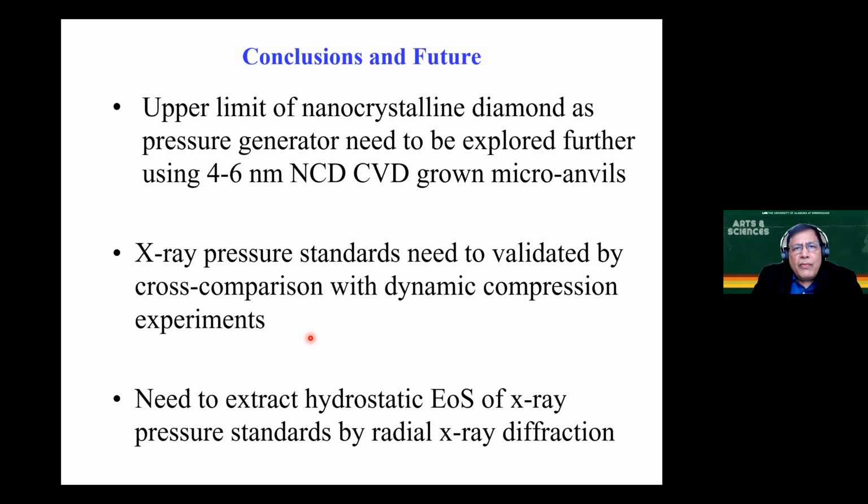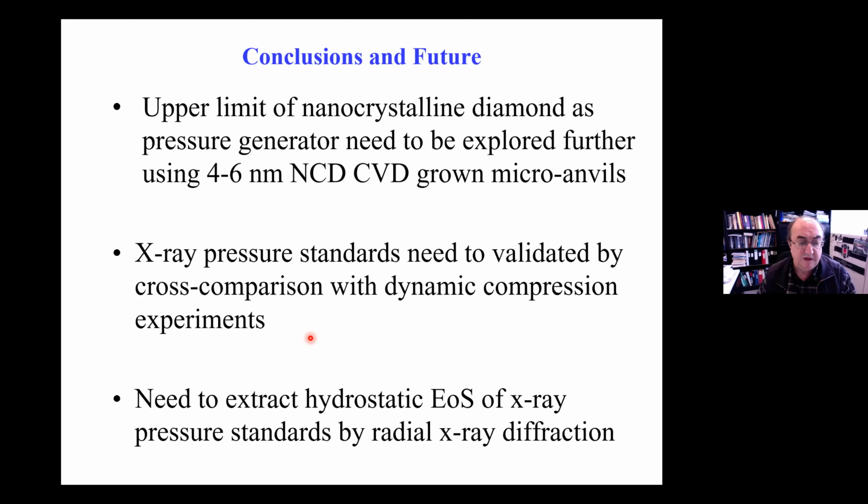No, I think with the nanocrystalline diamond, the mechanism is not dislocations moving through the individual grain, but more to do with grain boundary sliding. I see. So it's a different mechanism. I think that's an important point. When we are building a DAC, of course, we have to pay attention that the maximum shear stress is not on the 111 plane, where the cleavage energy is the lowest. But for the nano diamond, it's an entirely different failure mechanism. It's more to do with the grain boundary sliding. Right. Thank you.